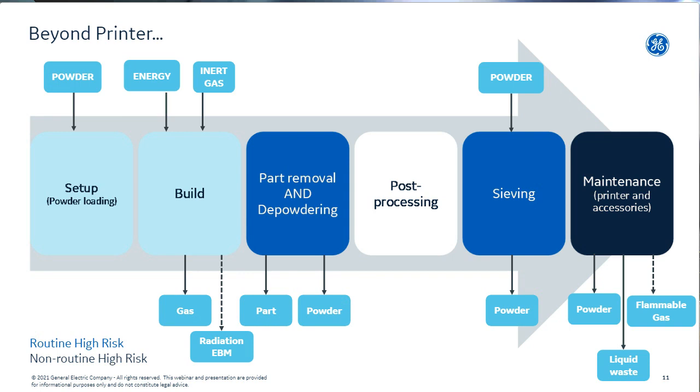They are either routine, because when you're utilizing a printer, you want to utilize it very frequently and often. So this printing activity would be something routine. But then some maintenance activities may vary. That can occur when changing, as an example, electron coils in the EBM systems after 400, 800, or 1,200 operation hours. So these are non-frequent, non-routine tasks that also need to be considered in your overall environment.